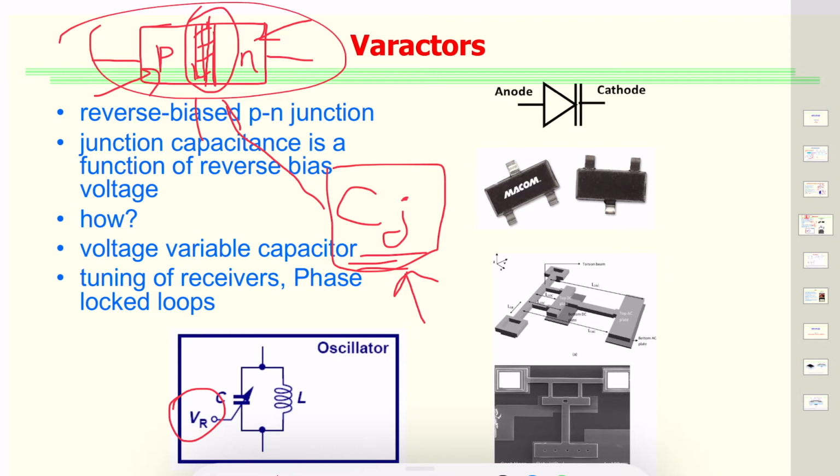We are using diodes in reverse bias, and the voltage is going to change the capacitance across that diode, the charge carrying capacity. So we make these devices to make the capacitance a strong function of the voltage by changing their physical parameters. There's more to that, but this is how these are made. These are actual pictures of those.